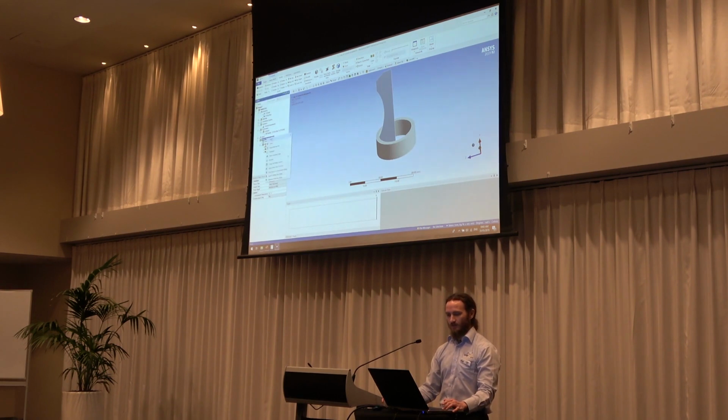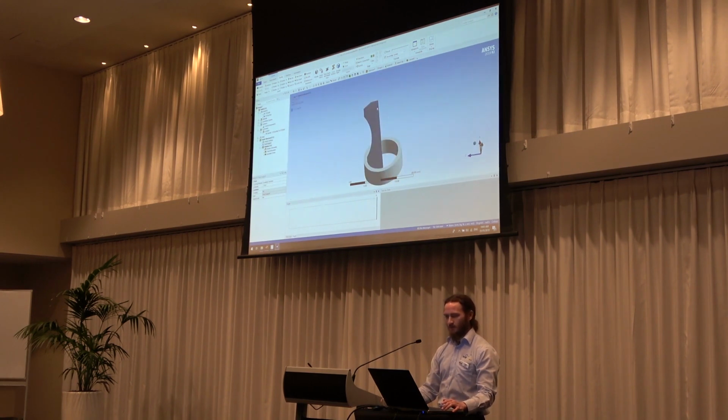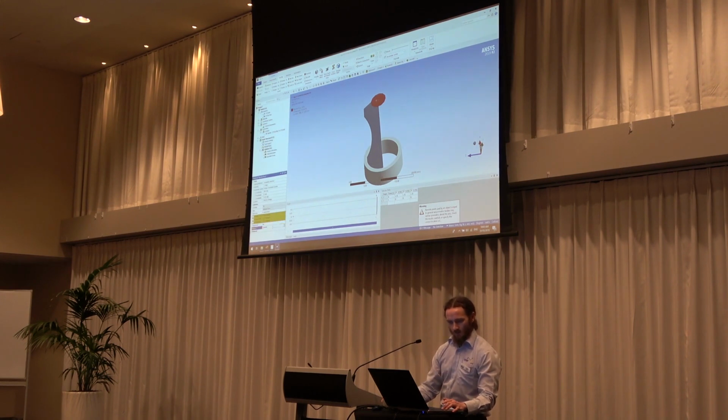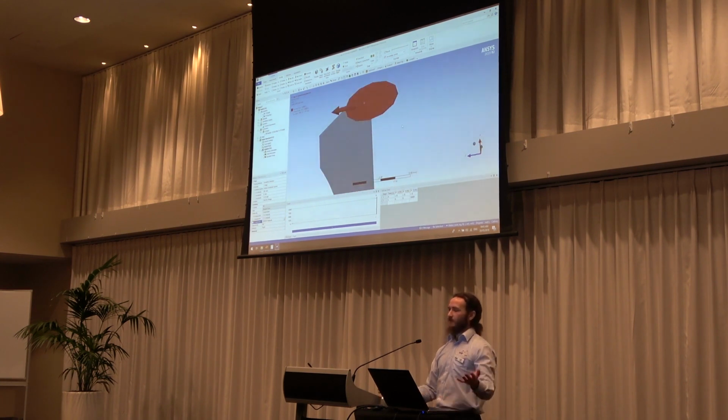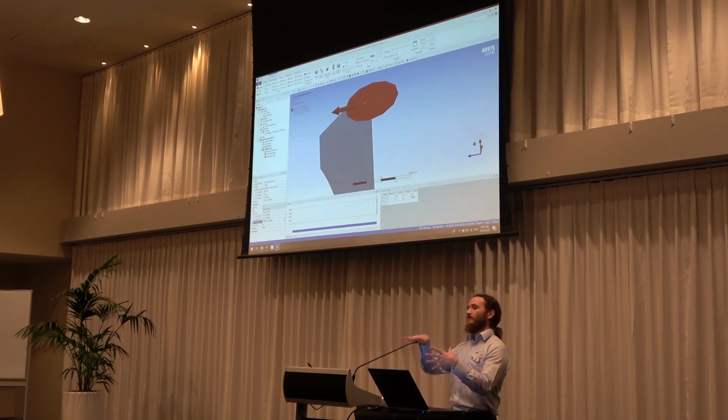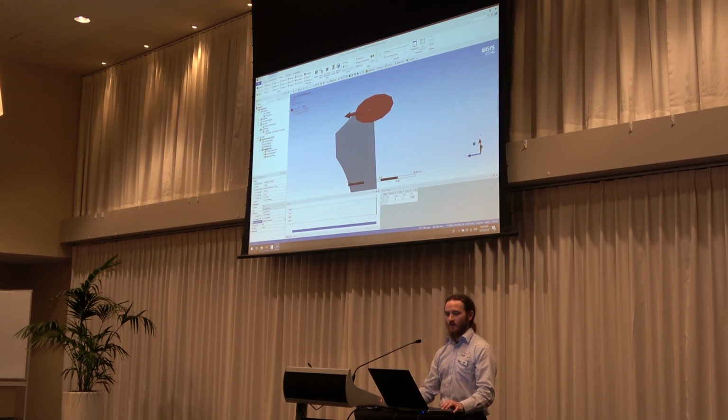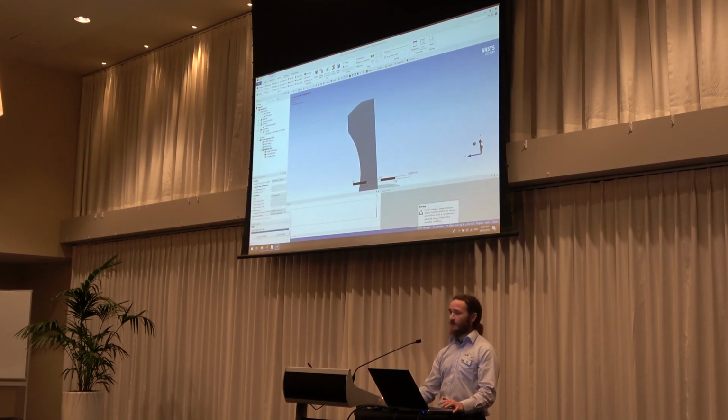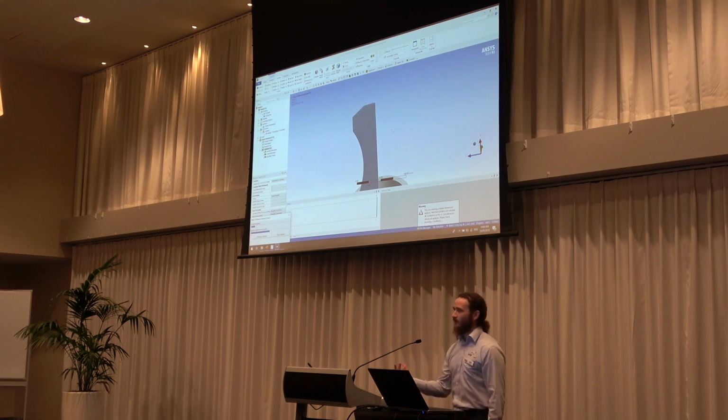And I'll put some boundary conditions in here. I'll insert a fixed support. And I'll put a remote force. So select that edge, insert a remote force, set it to rigid, and set it to 10,000 newtons in the Z direction. You can see I've selected an edge, but because it's a general axisymmetric body, it's applying it to the full surface of the 3D body that it represents. Then I hit solve. That obviously is not an axisymmetric load, so you couldn't do that in a normal 2D axisymmetric simulation. It wouldn't make sense.